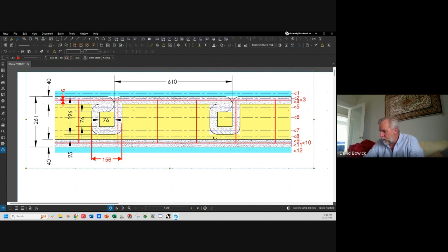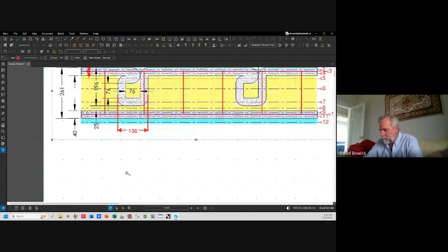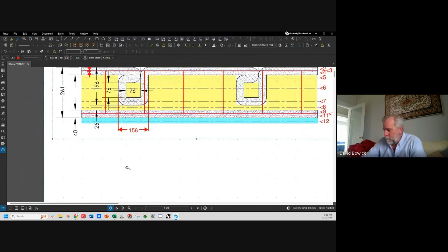Then there's the thermal break layer. We've said that it's 25 millimeters thick, where there's no concrete crossing. And then we've got 3 layers of our exterior shell, and then we have our exterior air film. So we have 12 different layers. This is going to give us lots of practice calculating this one. So, zoom back out here.